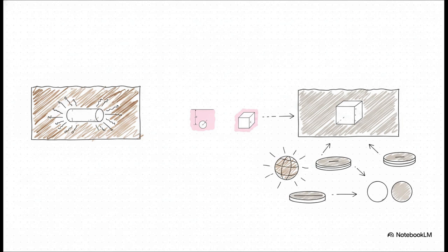On the left, there's a horizontal cylinder buried in a semi-infinite medium, which is perfect if you're trying to figure out heat loss from an underground pipe. On the right, totally different geometry, a buried cube. Our source gives us a huge table packed with specific algebraic formulas to find S for both of these, plus buried spheres, parallel disks, eccentric cylinders, you name it. It takes these insanely complex multidimensional fields and turns them into plug-and-play algebra.